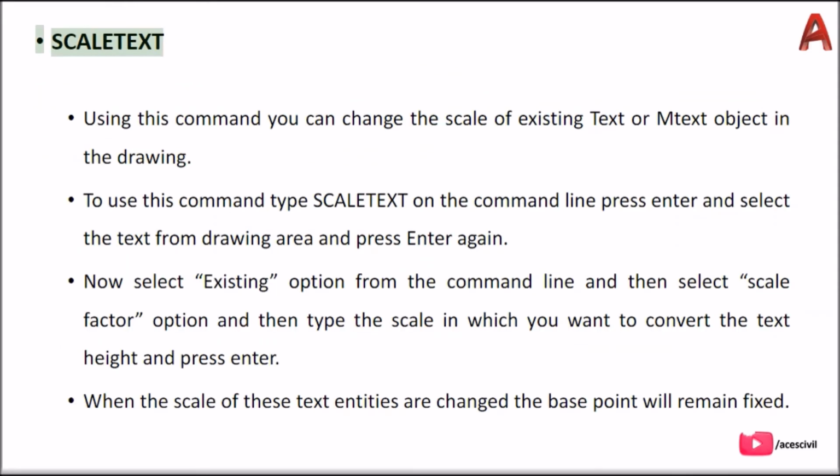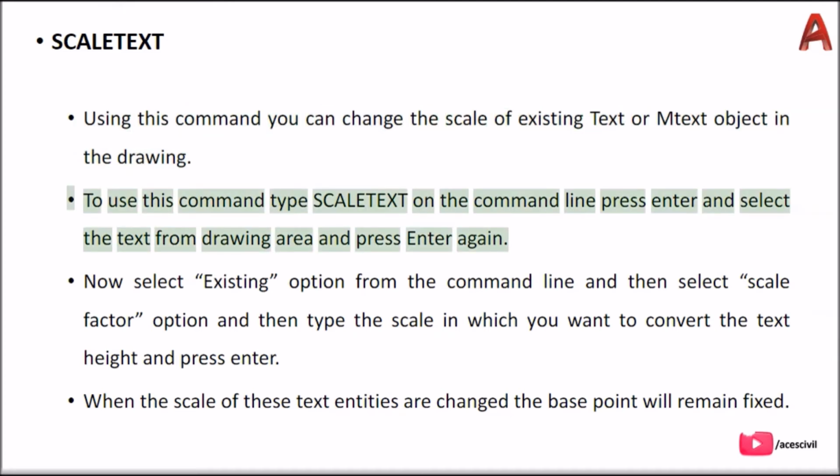Scale text. Using this command you can change the scale of existing text or text objects in the drawing. To use this command, type scale text on the command line, press enter and select the text from the drawing area and press enter again.